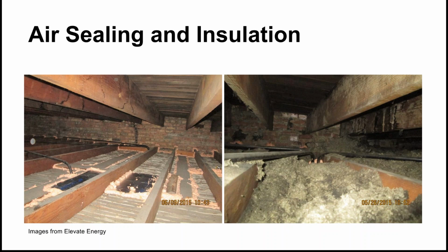So essentially you're not doing all that much by only insulating half of it. Having a continuous insulation barrier is the best way to prevent excess heat conduction. I have another example of this. This is the picture on the right here.